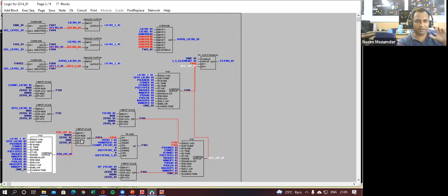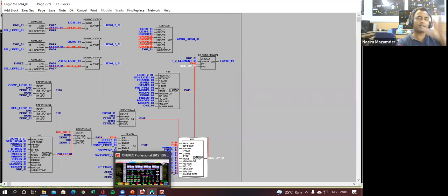This will be making the data value that is coming out of this PID fit in between this particular scale. Then there is something which is adding some values. Then you are manipulating it with the set points, and then ultimately the final PID value is coming. And this is it. So see how many things are there.